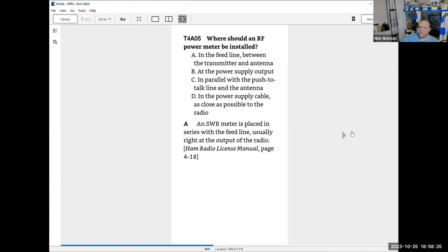The most accurate measurements are made with precision power meters, but you don't need it. You need relative for most operations. But for repairs and laboratory grade stuff, they use very precision power meters. And they use two of them, one measuring the forward power, one measuring reverse, and sometimes they use even three in the lab. That's not necessary for most ham stations. Those meters run about, I don't know, what's a Bird Wattmeter today, Thomas? Is it under $5,000? And three of them would be quite an investment.